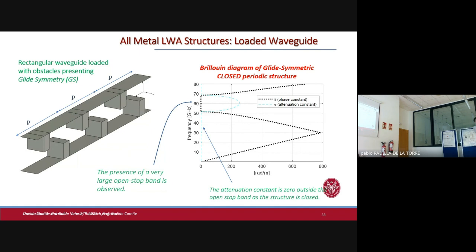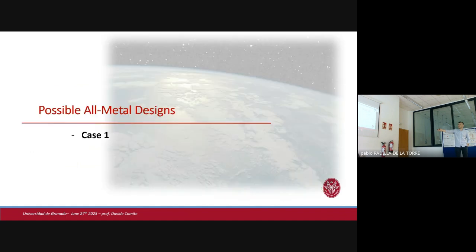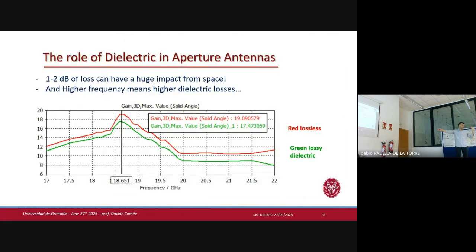Yeah, but they have a new life because higher frequency means a small percentage, a small fractional band, so you can still do something. You can define an instantaneous bandwidth by taking the minus 3 dB point. So if the bandwidth is not so large, there is room also in that case. And in any case, this kind of antenna, not a waveguide, was proposed by Oliner, who is the father of liquid antennas, in the 60s.